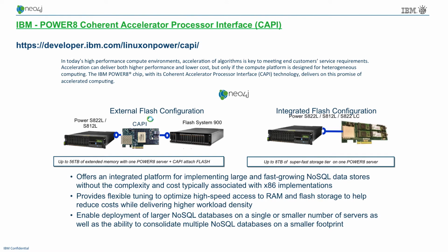So we do have both a protocol, and it manifests itself in the form of a card that can plug into our processors that basically contains an FPGA, and that FPGA is from Xilinx, extra memory that we can prefetch and put Neo4j data into, and then two NVMe sticks that we can use to extend our memory capacity from anywhere from 2 to 8 additional terabytes per server.